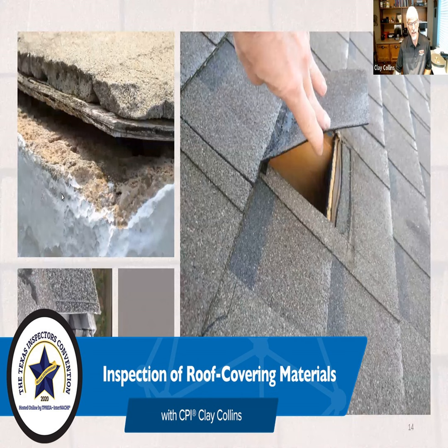But if it's installed against the roofing, it needs to be against the rafters so that you have the airflow between them. But the answer is yes, there are foil materials to be used as radiant barriers to be installed post-construction. The biggest problem with those is they can't get down into those very low spots at the eaves. But they're out there. What else?